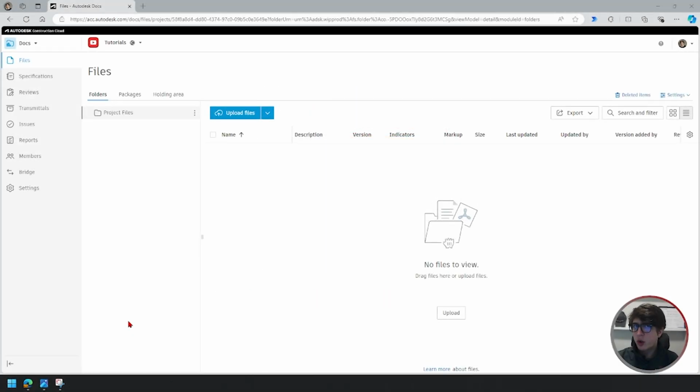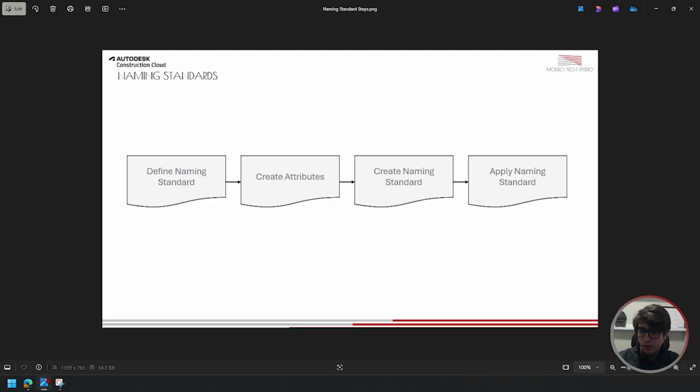In this video, I'm gonna show you how to create and implement naming standards in Autodesk Construction Cloud. For this process, we're gonna follow 4 steps: defining a naming standard, creating attributes in ACC, creating the naming standard, and applying that naming standard to any existing folder or any folder you create.